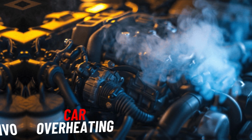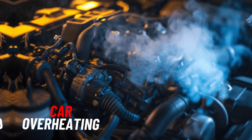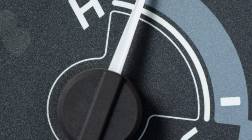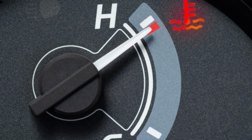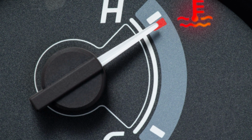Number 1. Overheating. The most obvious symptom is engine overheating. If the radiator is not functioning properly, it cannot effectively dissipate heat from the coolant. This can lead to the engine temperature rising above normal levels, which may trigger warning lights on the dashboard or cause the engine to overheat and possibly shut down.